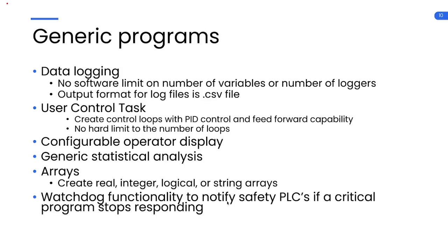And then we've got a watchdog functionality built in. So we've got this program that monitors whether or not all the other programs are responding and doing what they're supposed to do. And if they stop, then if you've configured that program as safety critical, then we will stop toggling that watchdog.